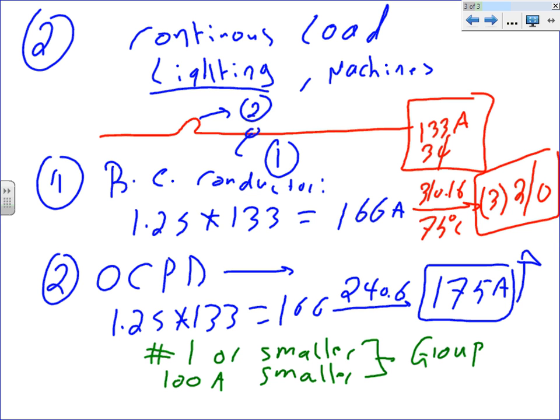You save money. If your load is also 100 amp or less, that's a good idea when you size a conductor for them to group it, which is basically the same size. Other than this situation, don't group. Does that make sense? Again, group in the pipe. Everybody knows what I mean by grouping. You bring the conductors, and you have a 4-inch conduit coming here and feeding 2 machines. You can do that. J-box, big full box, and you can do it.